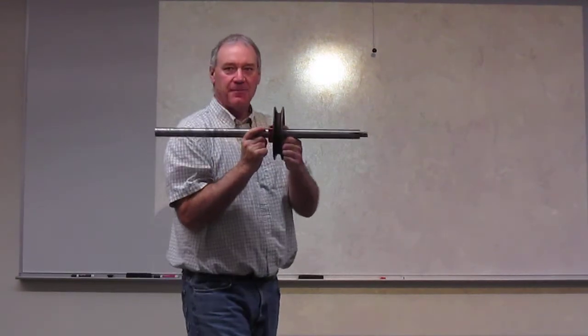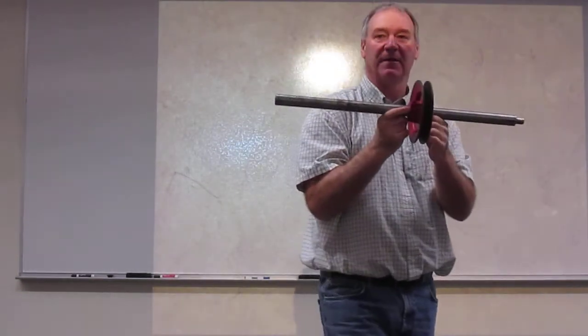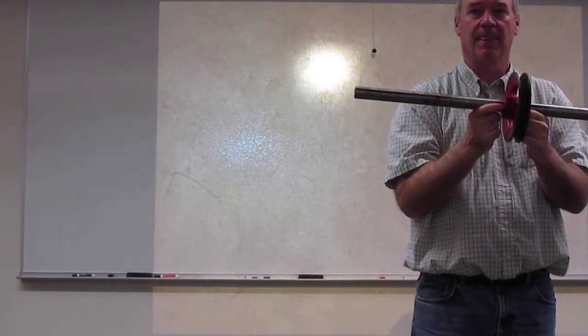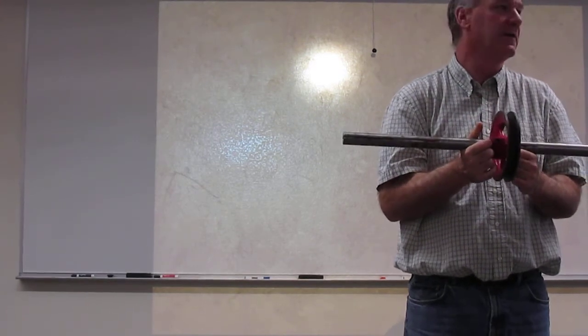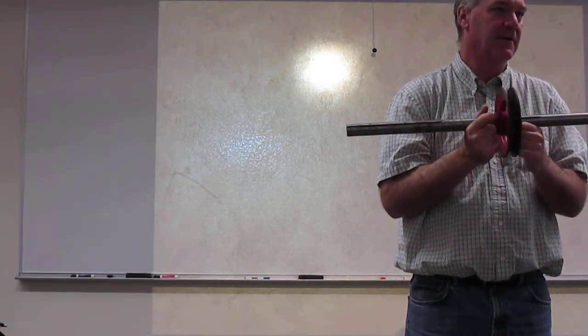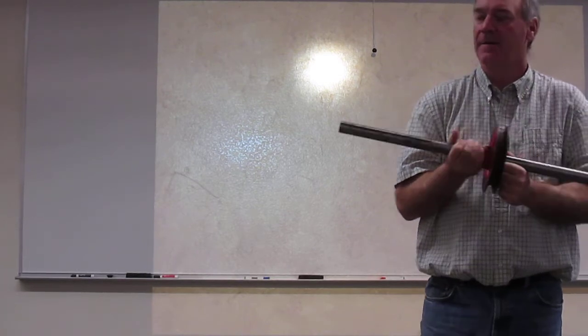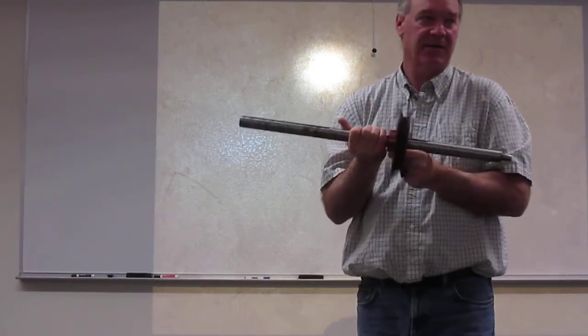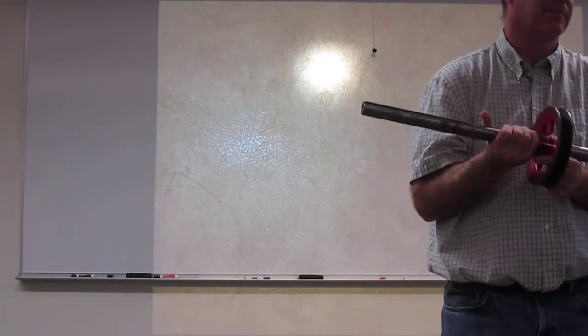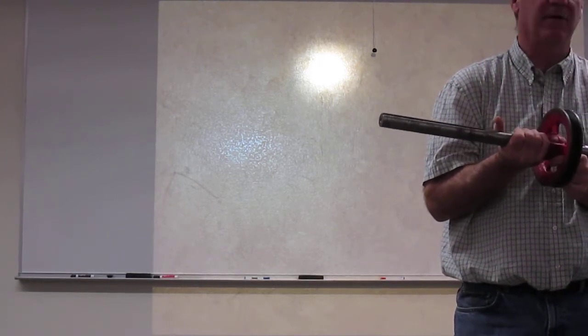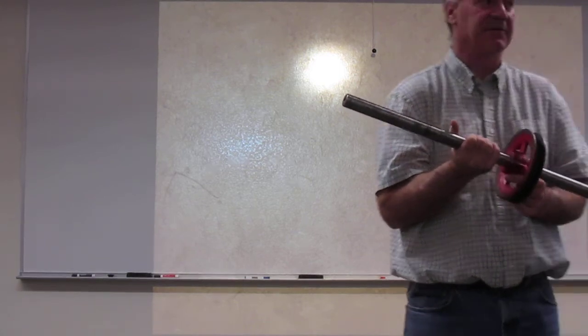Allowance happens when these two parts are constructed at maximum material condition. In essence, it's the tightest fit that can occur between mating parts. Okay, so allowance. The amount of slop that occurs at maximum material condition. Or the tightest fit you'll have. That's allowance.